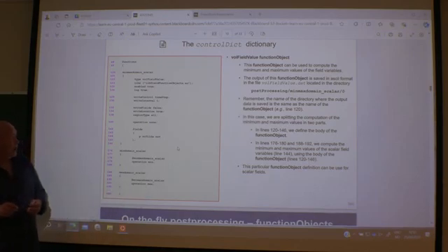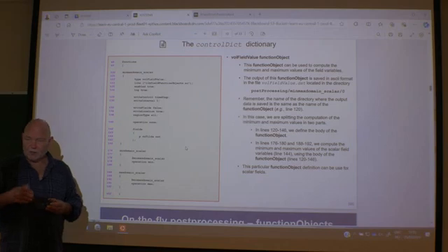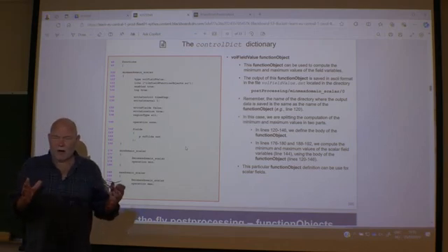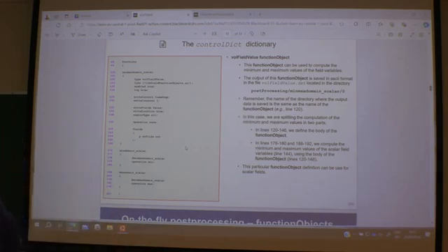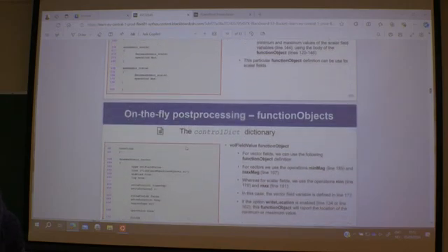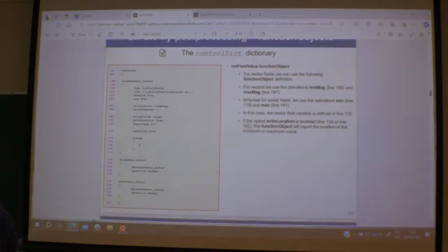So he will then print them out or save them in a file for you. It could be nice to know while you simulate what my maximum pressure and minimum pressure are right now. You can see that in the printout while he simulates. So then you can crash him if you see this goes totally bananas. Same with the velocity, but that's a vector, so it has a different setup, of course. But it might be a good idea to print these out during simulation.